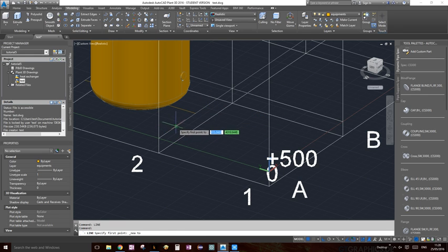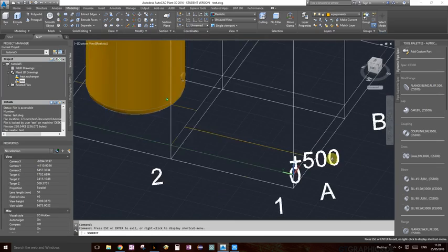So what this one does, if you're close to a line, it would just keep it there. So let's choose this line, and then we're going to become perpendicular to that line over there, and that's it. Press escape to get out, and let's take a look at the line. Do you see what I've done?